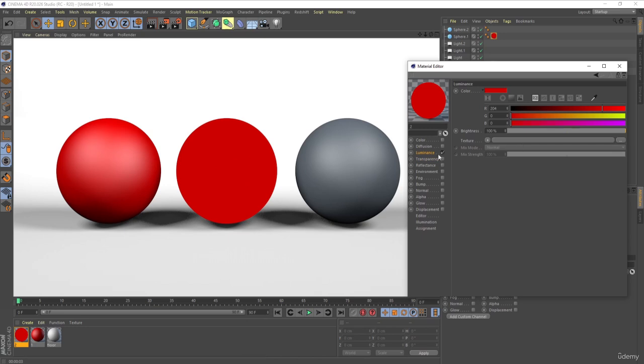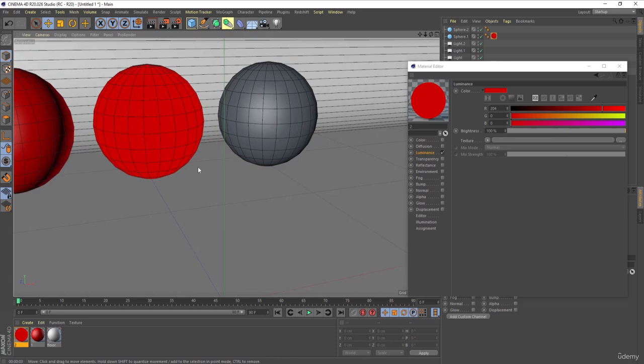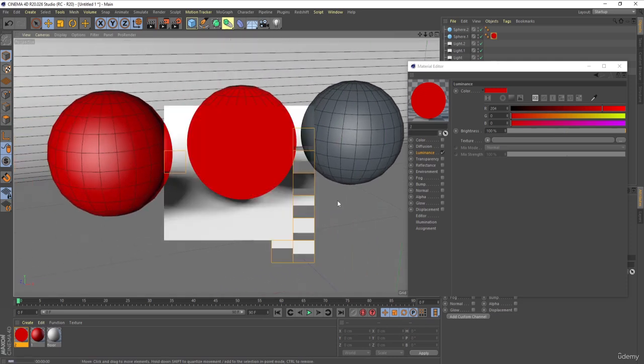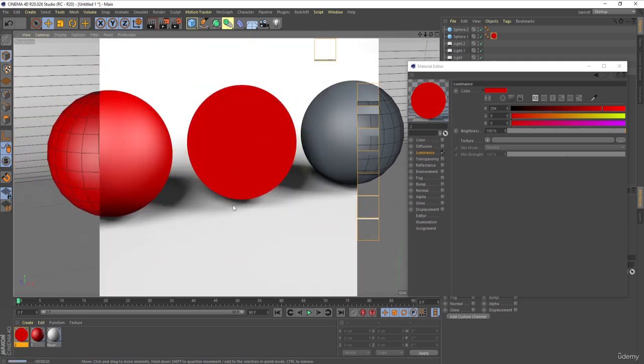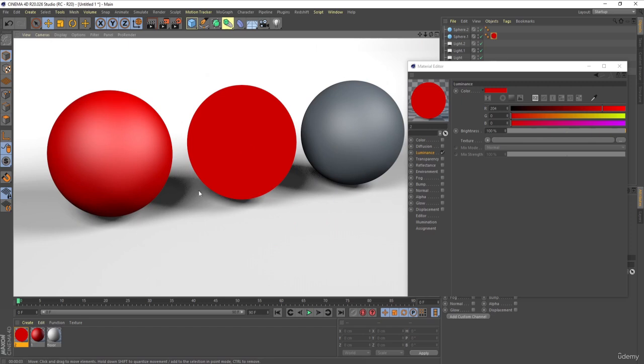So basically this option is useful whenever you want to create 2D animation or something similar in 3D software. That's where this type of color channel is useful. Basically it will look like you are creating some 2D animation in 3D software. Even if I rotate it over here and hit render, as you can see, we will get all the extra information like shadows and so on properly, but we will not get that three-dimensional look on this object because we have applied only luminance.